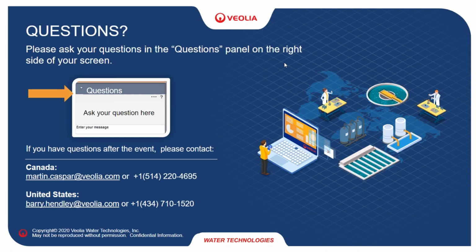You also grab it at the inlet to the hydrocyclone, and that's the more basic, because then you could use the whole inlet flow, 34 meters cubed per hour, or 80 GPM, in the calculation. So there are two places, but if you grab it from the underflow of the hydrocyclone, you have a better idea of how that centrifuge inside the cyclone is working.